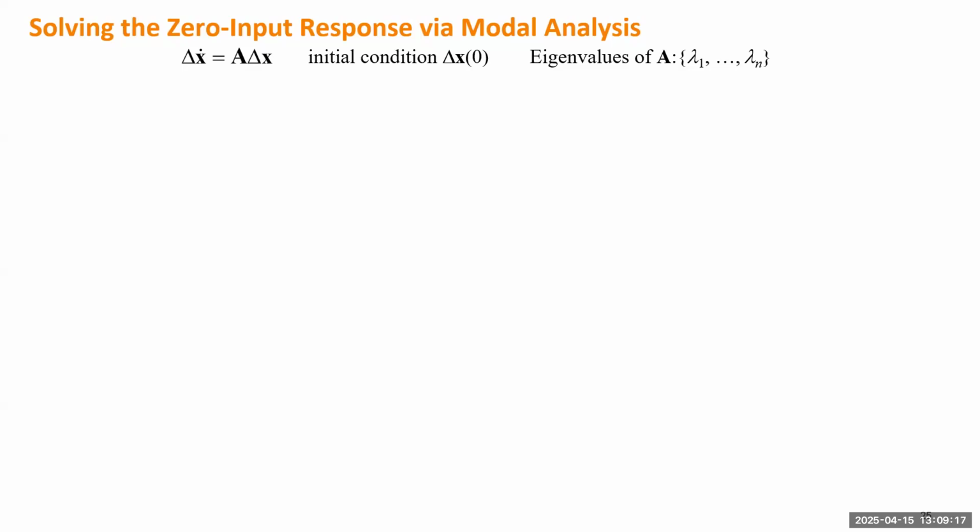Because we already have the linearized version of the power system, we just take this standard process to study the stability. So here we assume the model is a power system, but the entire approach can be utilized for any dynamic system if we focus on the oscillatory modes. We assume there's an initial condition, and we have n eigenvalues. We can just treat n as an even number.